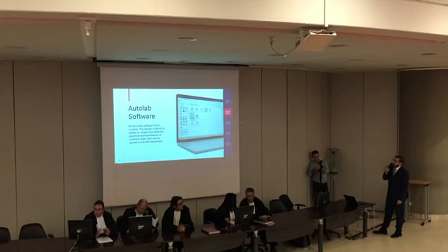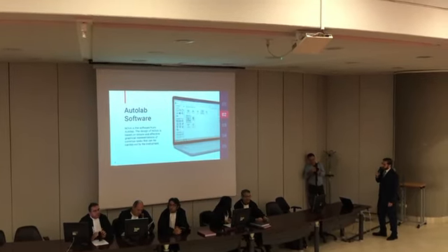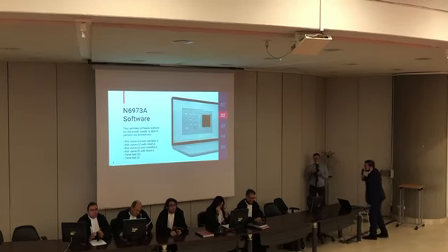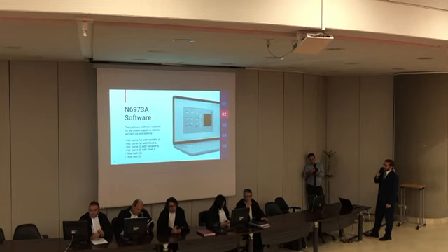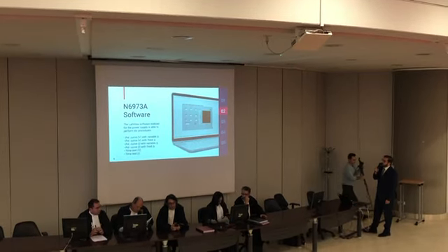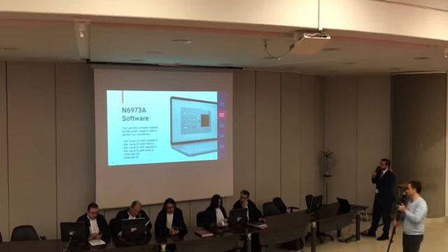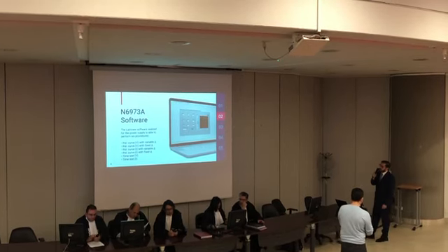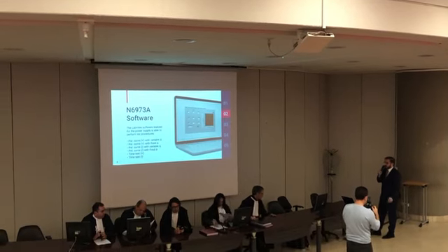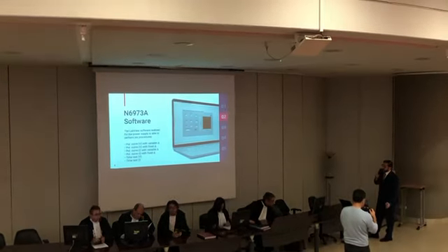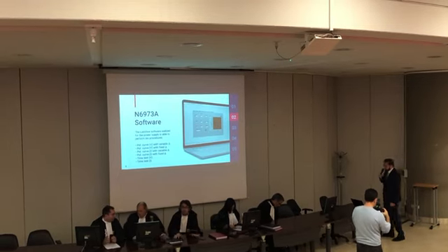Autolab has its own software, which is called Nova. Instead, the Keysight power supply was not equipped with its own software, so part of the work was dedicated to the realization of LabVIEW software. In particular, this software is able to perform 6 procedures: a polarization curve with variable step or fixed step, both in voltage or current mode, and the time test.